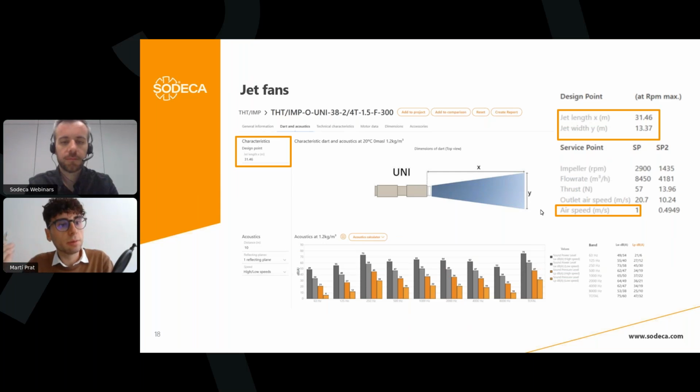So it can be possible that the airflow that you get from the pollution control is higher than what you get in case of a fire, for the smoke extraction. So you always have to consider the highest airflow that you get from this calculation.